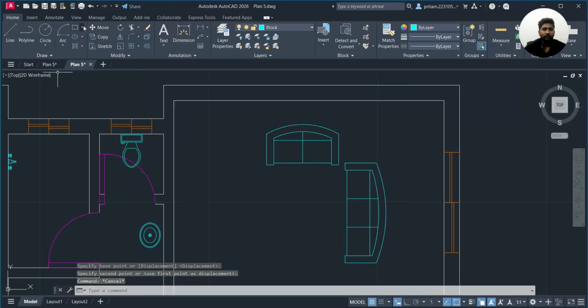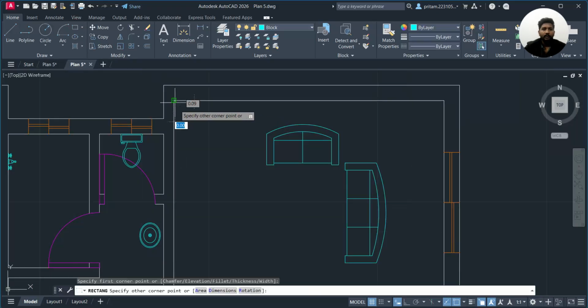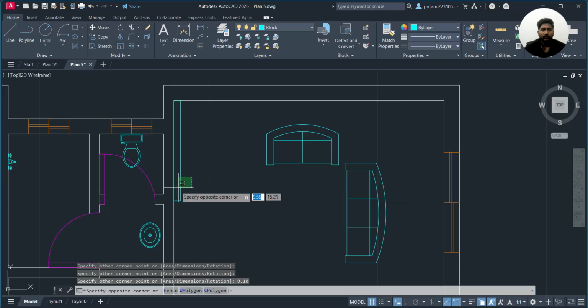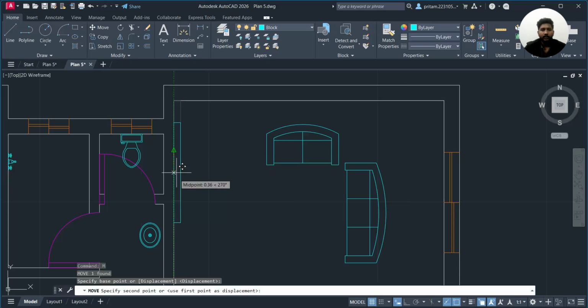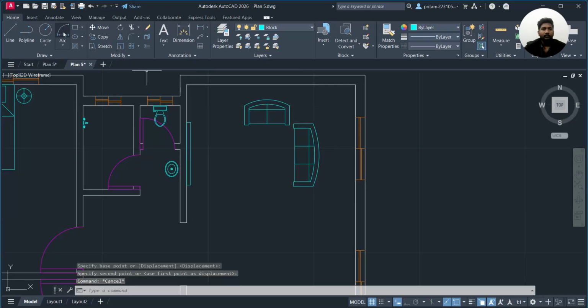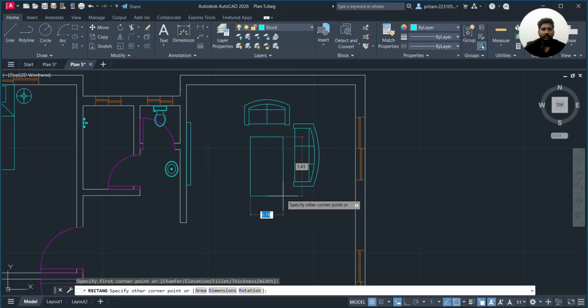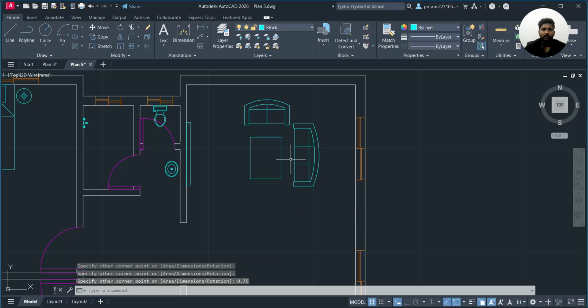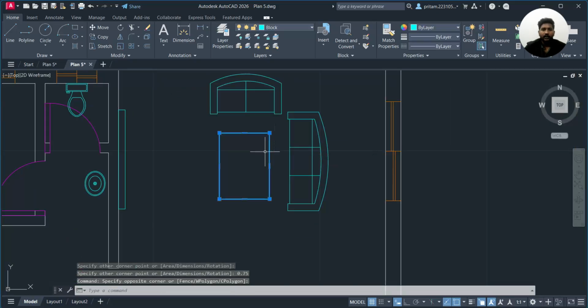After that, we have to make a TV, a television here. We will make it with 0.1 tab. The size of it will be 1.2 or 1.5. Let's say 1.5. Just move it forward from its midpoint to the midpoint of this line, so it is present here. And we need to add a table also. For that table, select this part and choose 0.75, tab 1, tab, and enter.